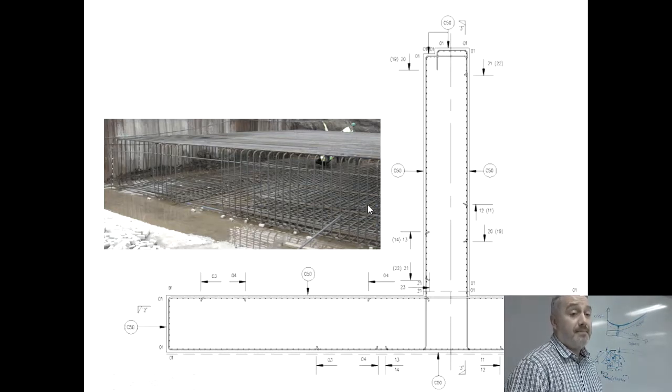He said that a lot of times when he was putting steel in, as long as you got the cover from the outside of the concrete to the first bit of steel correct, as long as that was 50, it didn't really matter what they did inside the steel cage, because they knew that the civil engineers largely didn't spot it. Has anyone had to do any reinforcement checking at all on site?